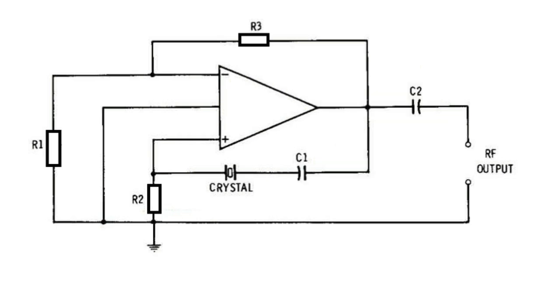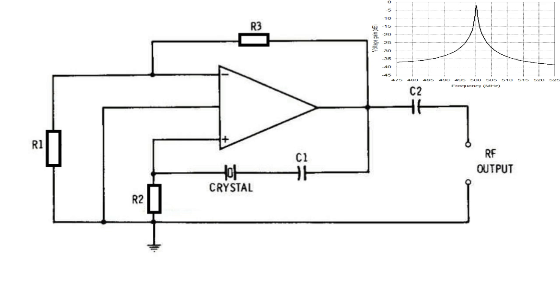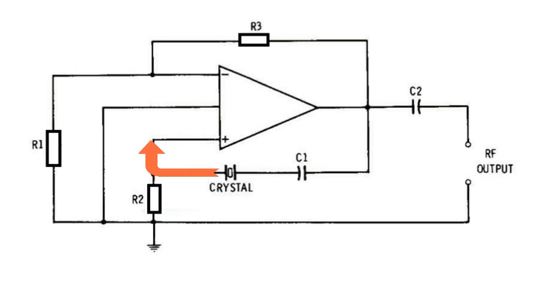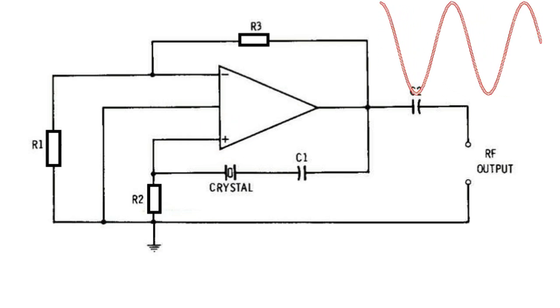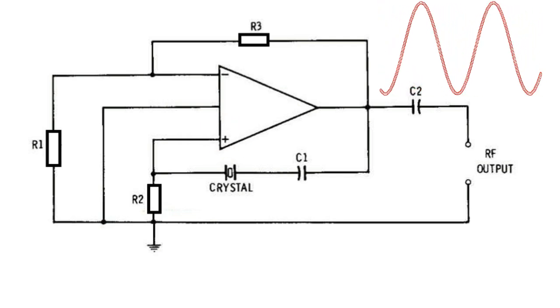In this configuration, the crystal works like an exceptionally high Q bandpass filter within the op-amp's positive feedback loop. The positive feedback current transferred through the crystal builds up a voltage drop around resistor R2, which is utilized on the op-amp's non-inverting input pin of the IC. This finally forces the circuit to oscillate with the crystal frequency.